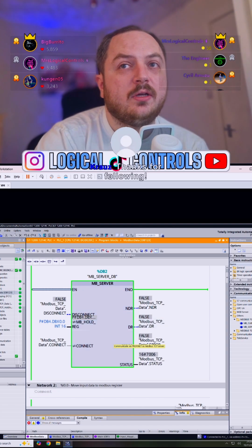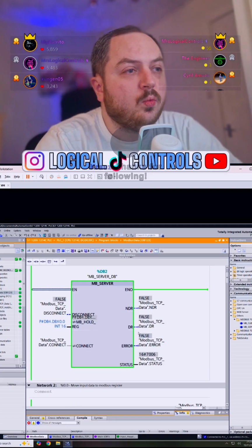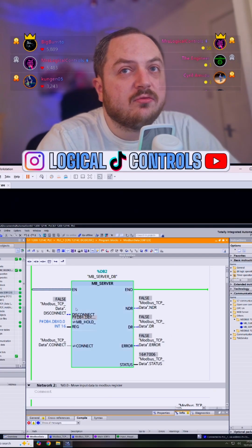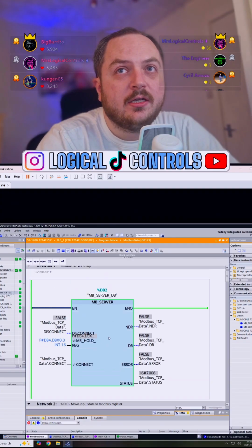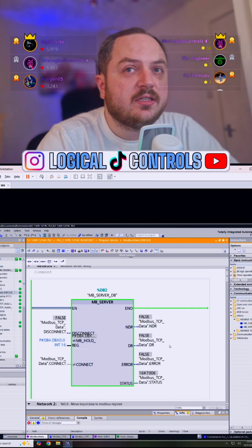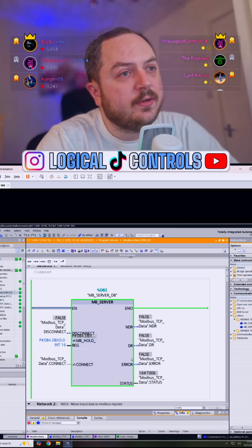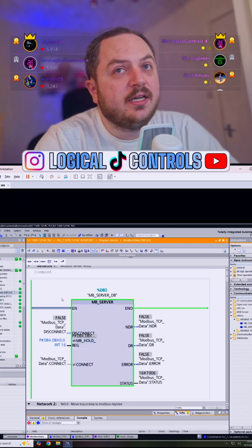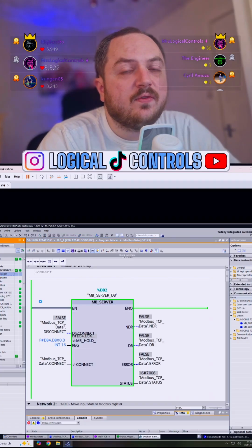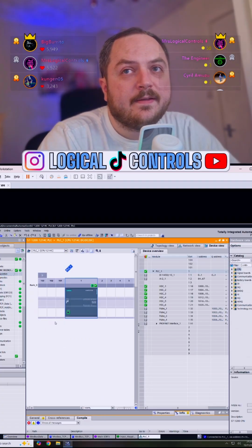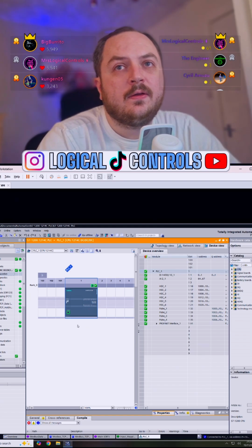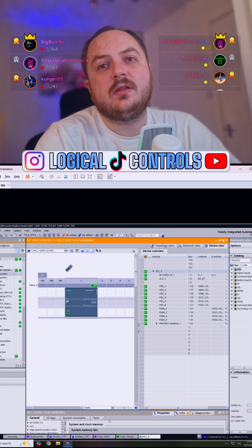In Mitsubishi, it's way easier to set up Modbus. It's done through configuration rather than done in the logic. Here, this is a ladder rung. I've had to bring in a block to do it. I've had to map all this data to it. In Mitsubishi, it's almost as easy as if I went into device configuration and double clicked that, and I should get something at the bottom.